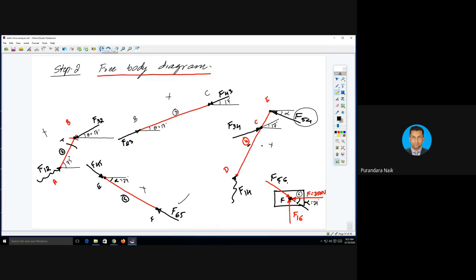What is given in link number 4? There are 3 forces, right? One is F54. F54 is always equal to F45. You know the direction of F54 at an angle of alpha. Alpha is 27 degree. F34 is also known. It is at an angle of 17 degree. See the link number 4. But I don't know the direction of F34.